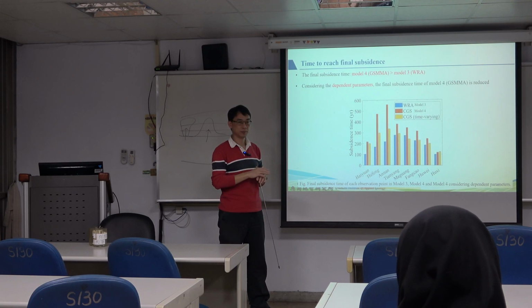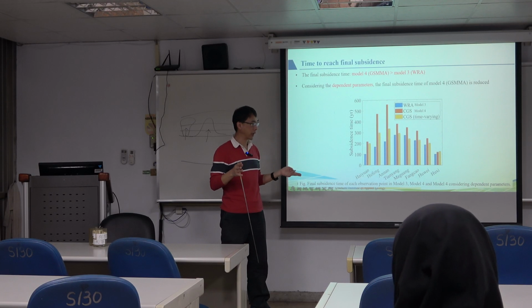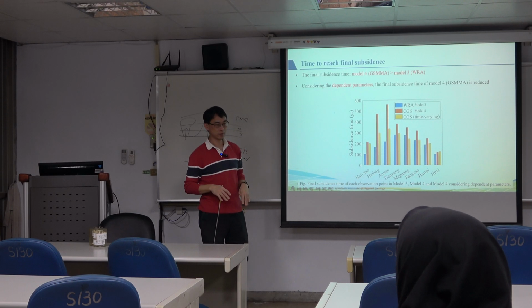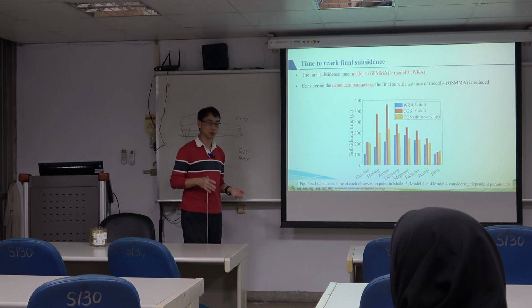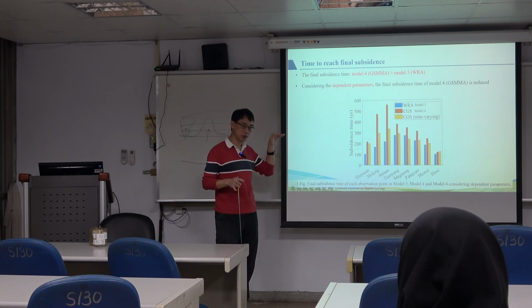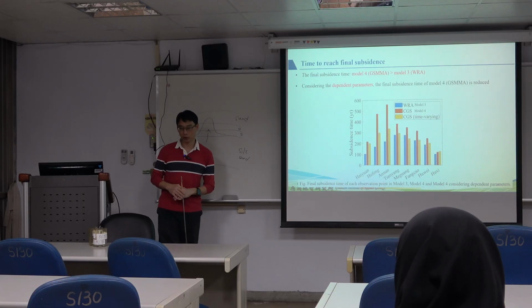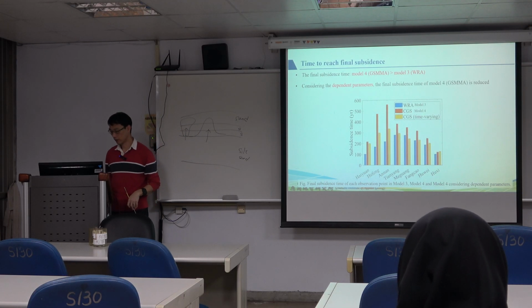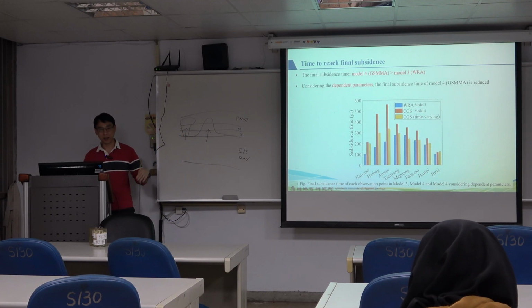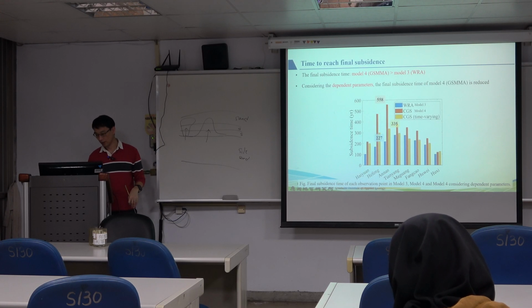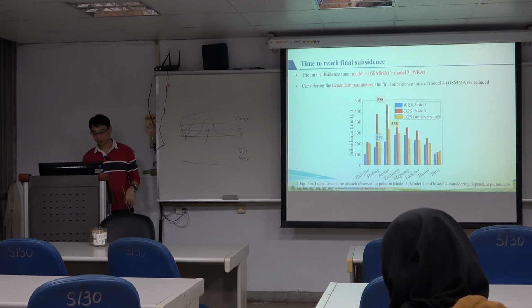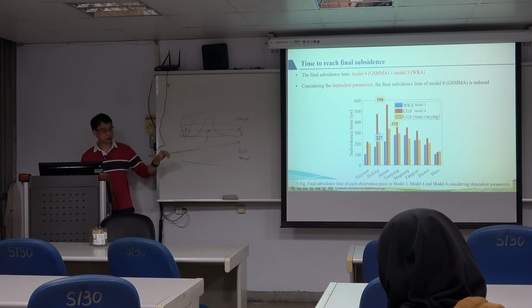So that means WIA's strategy is incorrect. I tell them that you cannot just stop pumping. If you stop pumping, you cannot solve the problem. You need to have recharge. If you do not have recharge, you cannot solve the problem, because there is residual consolidation head there to continuously induce the problems. Yeah, this is just some of the results for your reference.